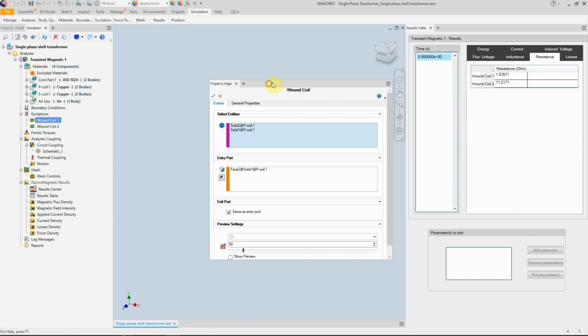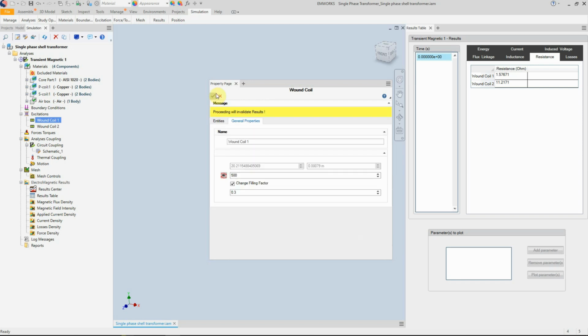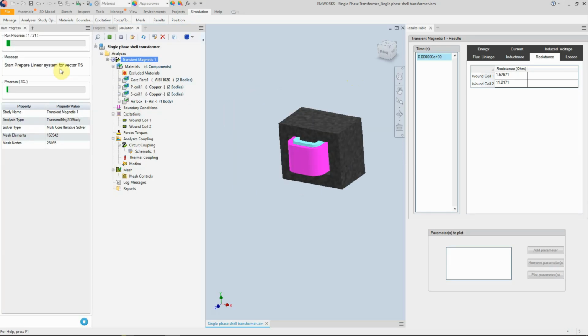Coil 1 has 1.5 ohm as the resistance. Let's make the number of turns 500. If we make a mistake and consider the resistance will be doubled, which in many designs happens to me myself, and I consider that the resistance will be doubled. Of course, it will be 4 times more.